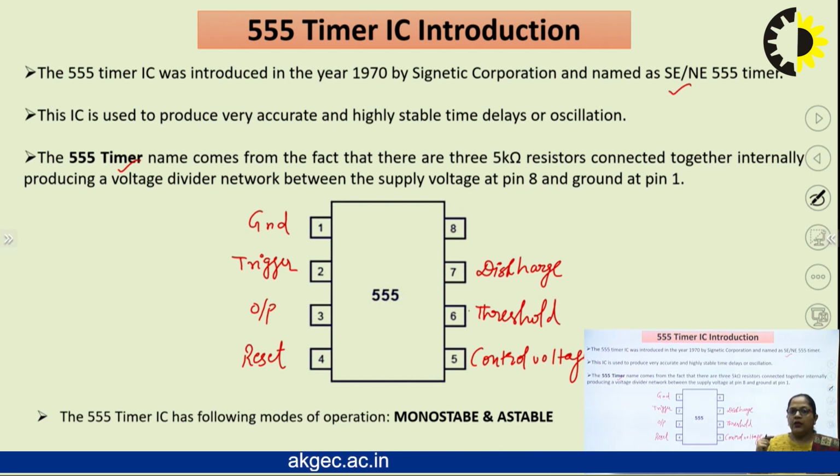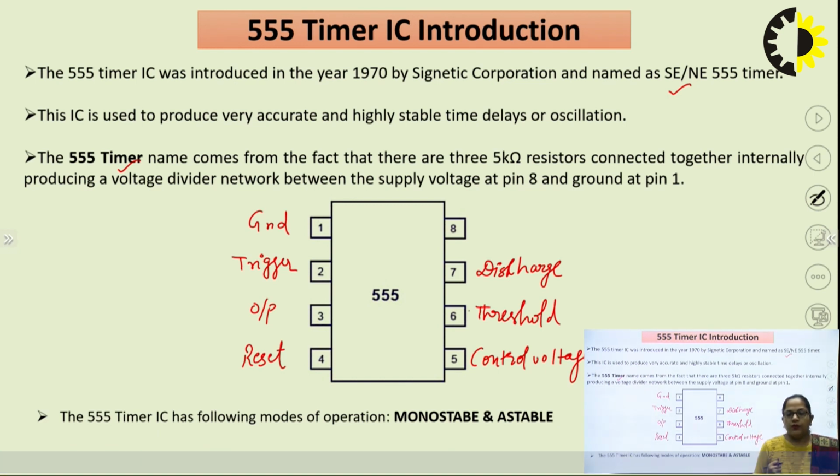If binary 0 appears on the base of the transistor, the transistor operates in cutoff mode, and a capacitor, which is usually connected to the transistor, starts charging. When binary 1 appears on the base, the transistor acts in saturation mode, like a short circuit. When the transistor is operating in short circuit mode, the capacitor starts discharging.